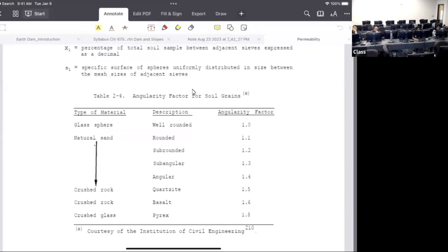If you know that there is a rainfall and you go to the site the next day, and let's say for the next 3-4 days there is no rainfall at all, then whatever moisture has infiltrated is basically traveling. If you are out of the active zone, and you ignore the first top 10 feet and look at the data in the lower depth, then you definitely can start looking at those numbers using resistivity to find out the permeability and the other results. It should work. Okay.